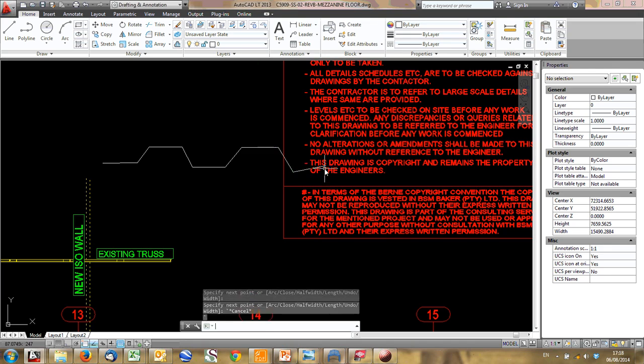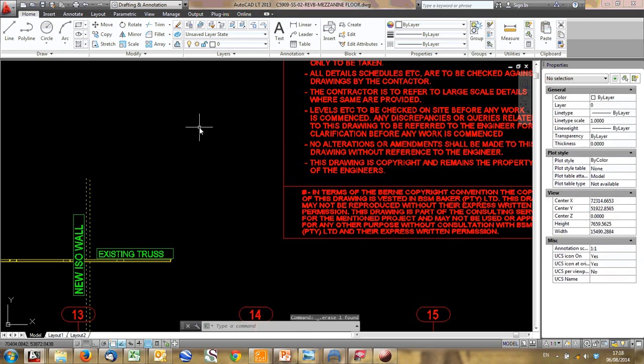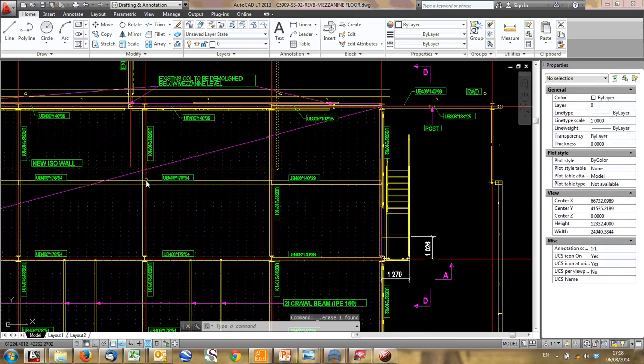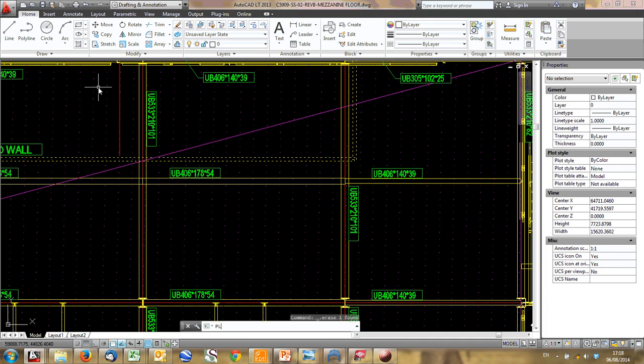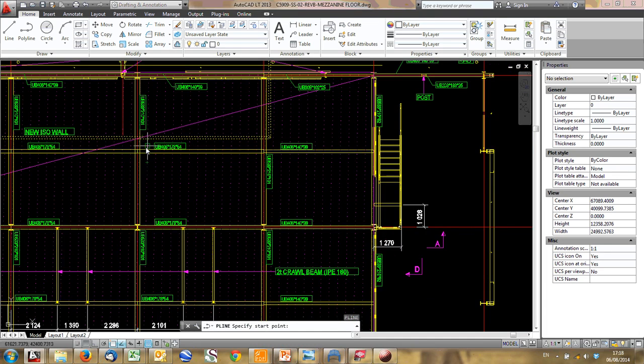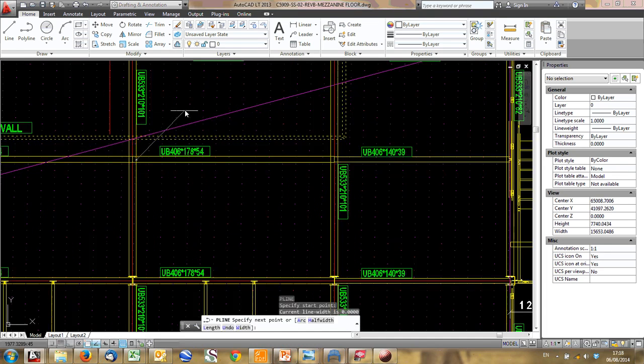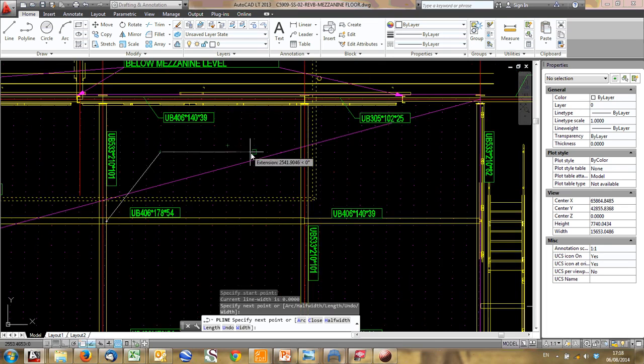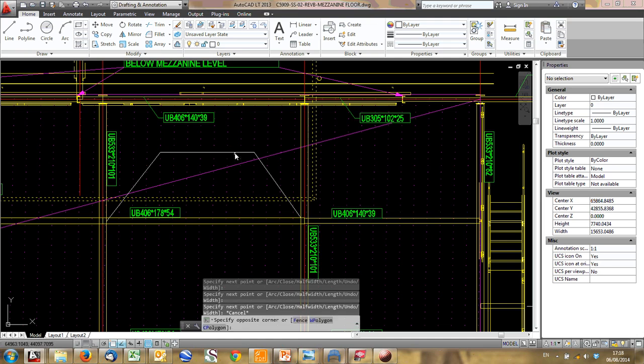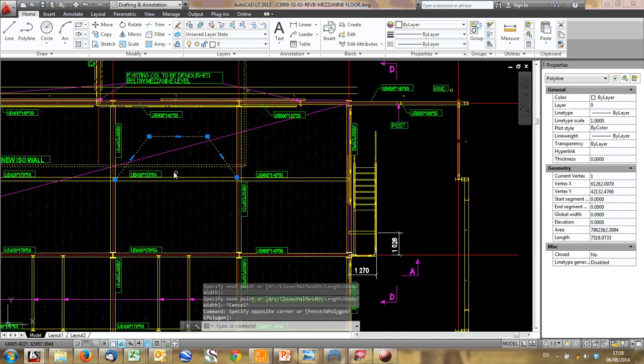This structure was actually flat. It was flat on the bottom, so it would span two ways. So you get triangular loads. So if you're going to analyze this beam, you might say the load acting on it looks something like that. And obviously you'd mirror this and you get the load on the other side, and then you can analyze it.